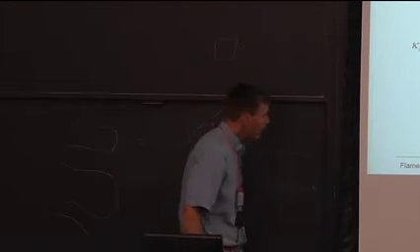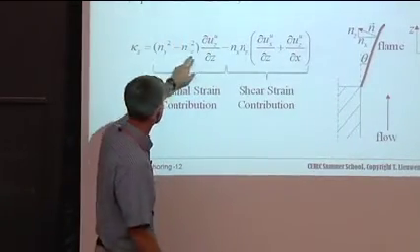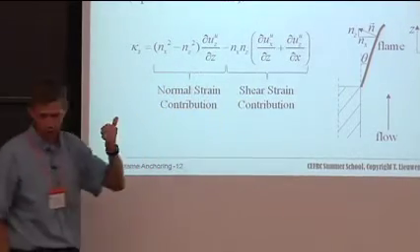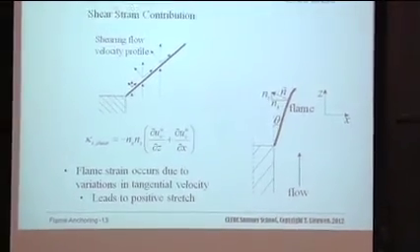Right? So, you can see that I have this normal strain. Well, that contributes to flame stretch through these terms. I have shear strain that contributes to flame stretch through those terms. So I want to unpack these a little bit. Let's start by looking at shear strain.